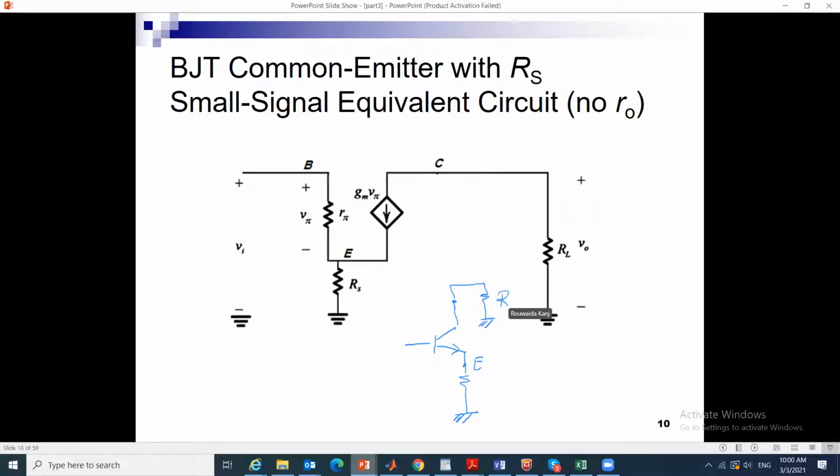to node C. And we said last time that the resistance Rn, looking into the amplifier from the base, if this is Rs, is going to see R pi for Q1. So if this is Q1, we're going to see R pi 1. This is the Rn that we will see, R pi 1, plus beta for the transistor plus 1 times Rs.